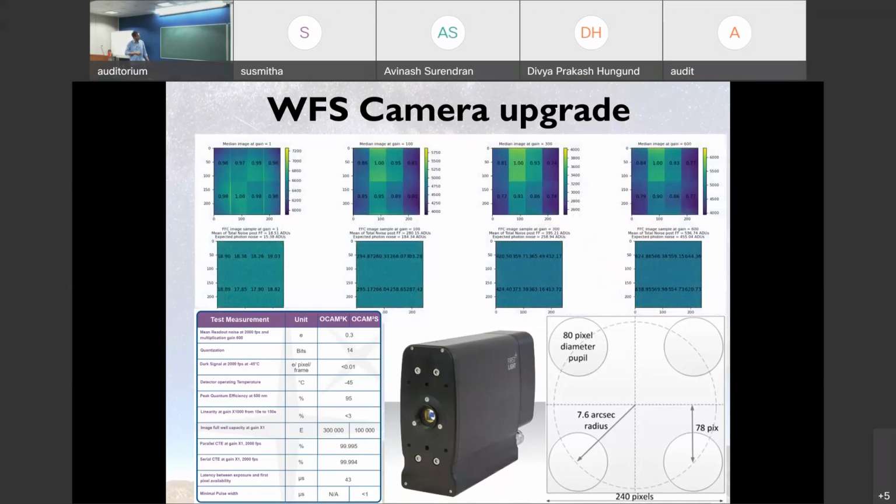But the problem is it's a very, very difficult camera to work with because it's very sensitive to over illumination. It's very sensitive to even shipping. We had one camera which got shipped where the capacitor of one filter tuning circuit changed a little bit, and it was having massive charge transfer efficiency issues.